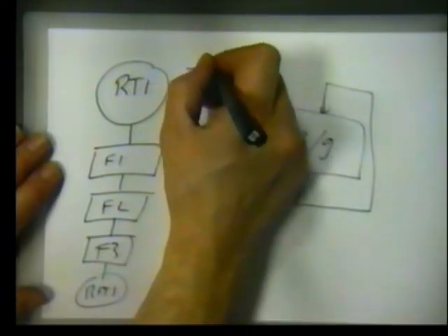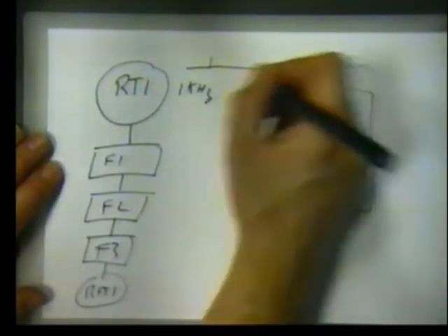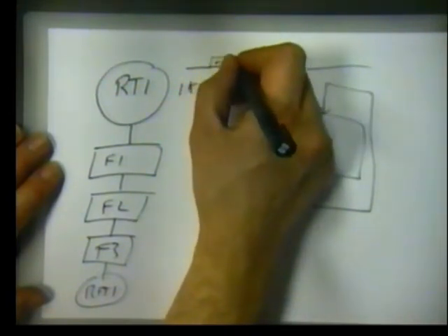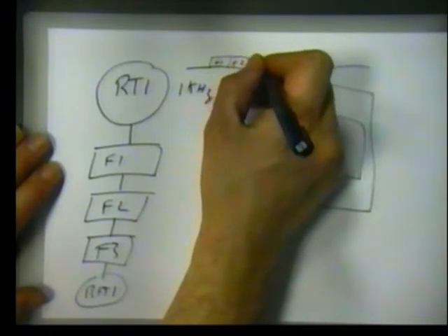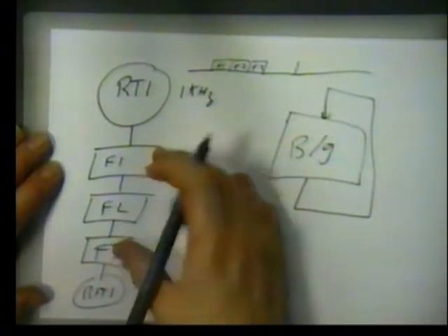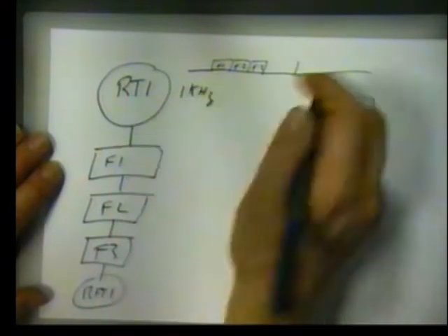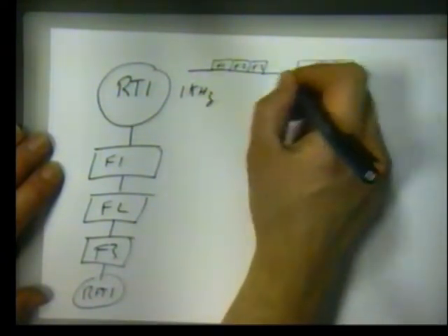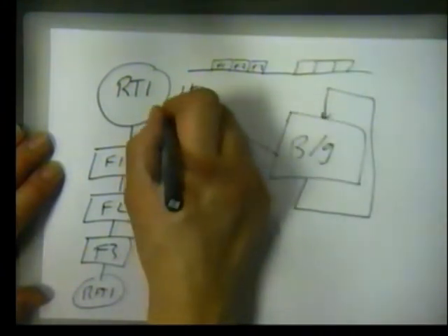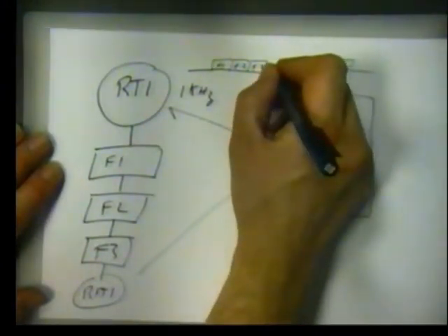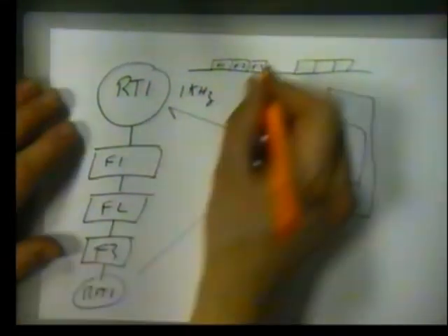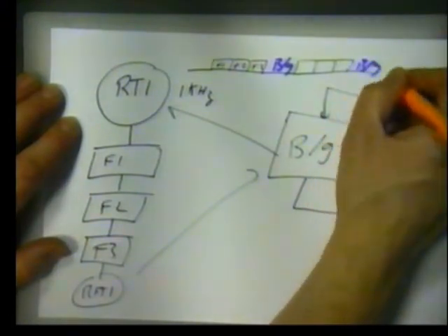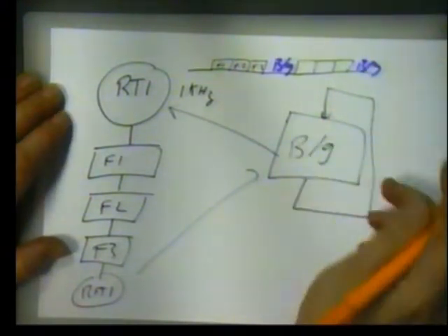We have a real-time interrupt occurring at this interrupt rate. We're executing F1, F2, F3. Now remember, the total execution time of all these three functions must be faster than the rate of arrival of the interrupt. They've all got to be done in that time. And then we will return, every time this happens, we go to there, we return to the background. So here, what we are doing is allocating all the available time to our background routine, slow processing.